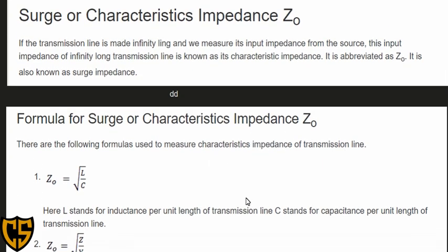Say you stand at the side of the line, and whatever impedance you see in that part, that is a finite length of the line that is terminated in a purely resistive load, for example, with the resistance equal to what we call the characteristic impedance of the certain line.